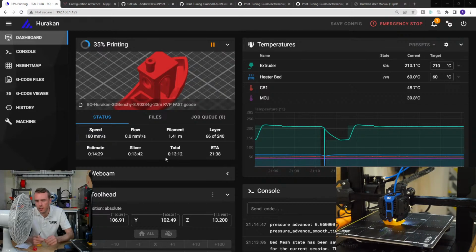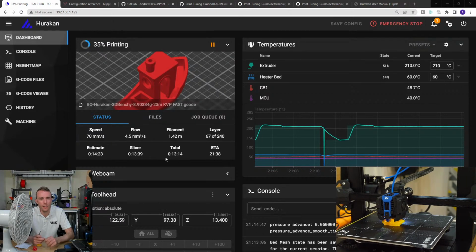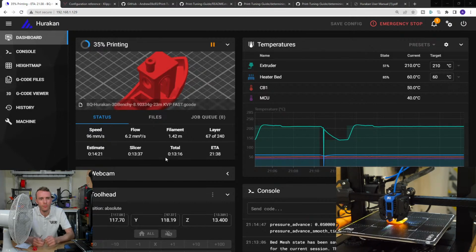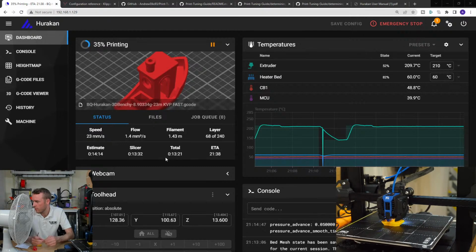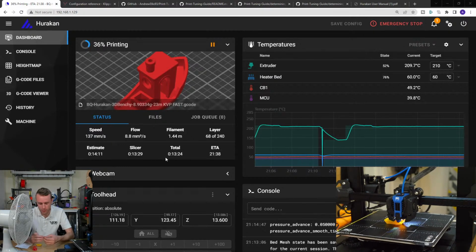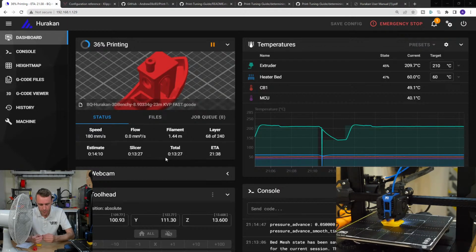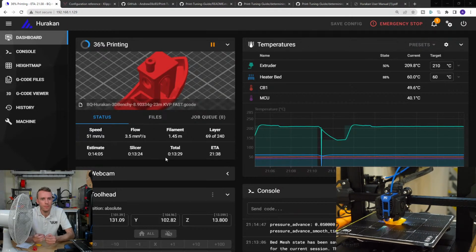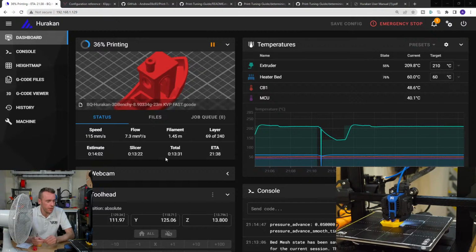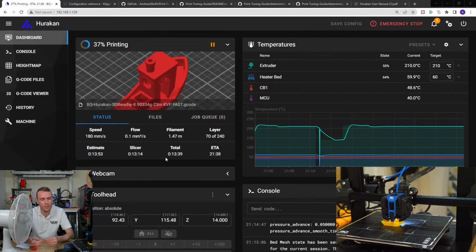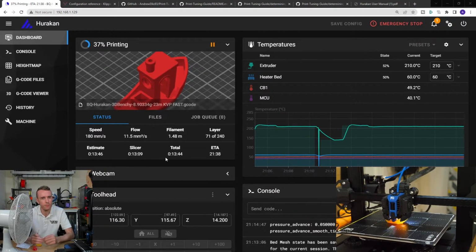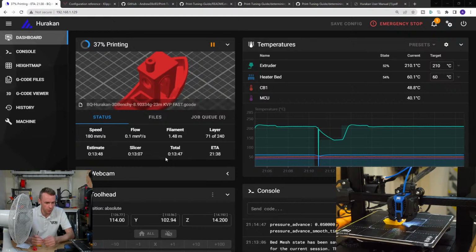Flow faster is a pretty general term. I've tested it quite extensively at this point. My testing is based on force. You can achieve a higher maximum flow rate with the same hot end with PLA than you can with ABS, because it requires less force to extrude than ABS at a reasonably high temperature for both.